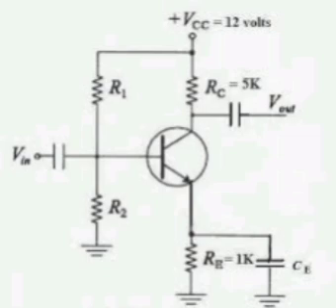For 10% voltage drop, E equal to 3 minus 3 into 10 by 100, 3 minus 0.3, that equal to 2.7 volts. R2 equal to IFSD Rm RH whole by E minus IFSD RH, R2 equal to 285.71. R2 should be changed from 200 ohms to 285.7 ohms to compensate for this reduction in battery voltage.